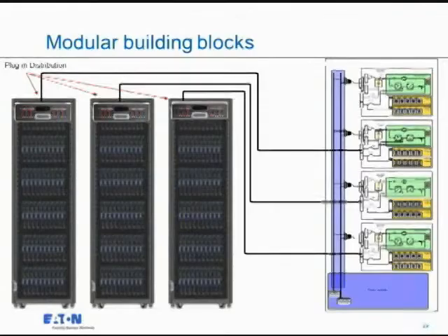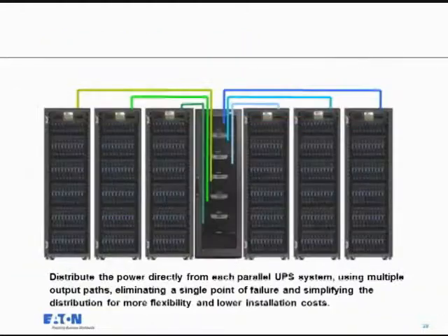Start with 12 kilowatts, add a rack of power equipment, add 12 kilowatts of distribution. Add a second rack, add a second 12 UPS, add more distribution. Add a third, add more distribution. So you add distribution as you add power. The only thing you really need to be concerned about is having sufficient incoming power to drive your ultimate end game. And, as I had indicated, make sure you put the extra module in it to gain that redundancy back and the reliability back on it.